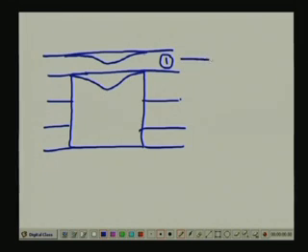Now, if in addition to it we have a large horizontal pressure acting on this particular slab, then you can easily notice that the problem of sagging is going to get accentuated, and this may become so severe that the slab near the top of the tunnel is going to fail.